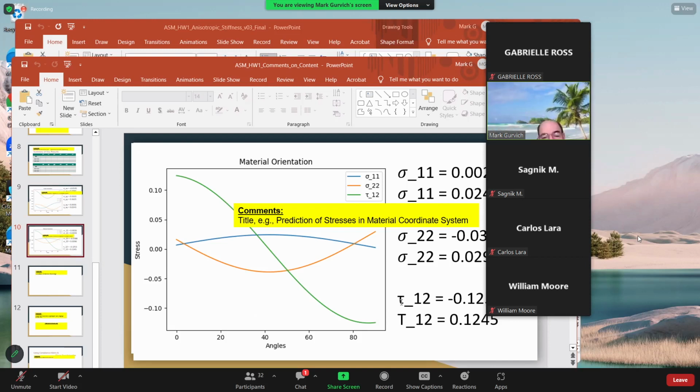So ideally, you want for fiber orientation 1 1 to have maximum, and for the opposite orientation 2 2 or 1 2, you want to have minimum. You could say blue is almost kind of, I can't say constant, but relatively small variation from here to here. But the green guy is moving with huge variation. The green guy is shear, and shear is a troublemaker.